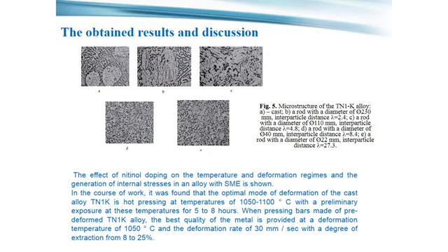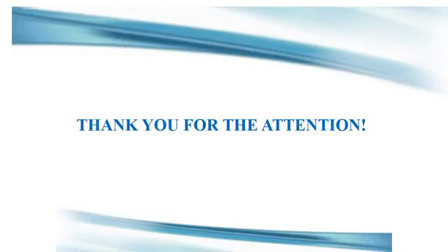They allow you to get parts with an operation temperature below minus 60 degrees, which is necessary for mechanisms of aviation and rocket and space technology. Further study of the properties of nitinol, such as the shape memory effect and the unique property of superplasticity, allows us to improve technology and apply such alloys in various industries, including robotics.